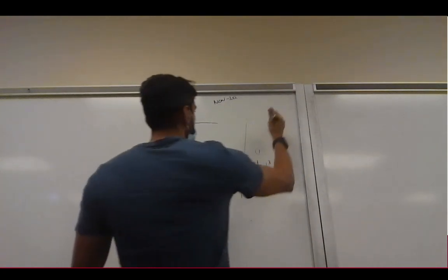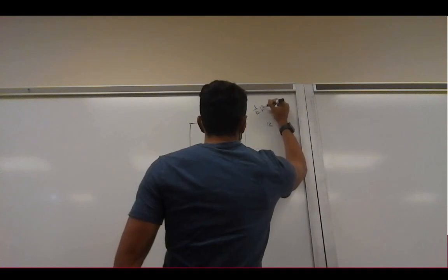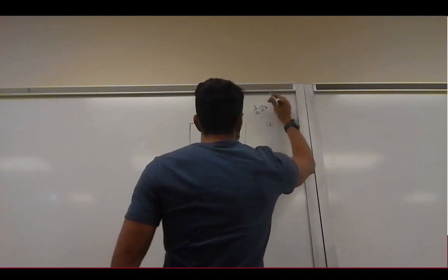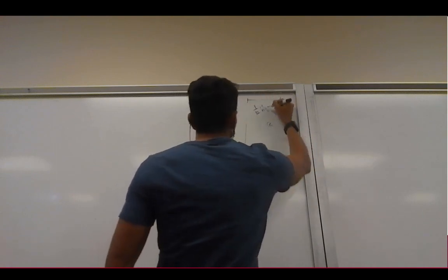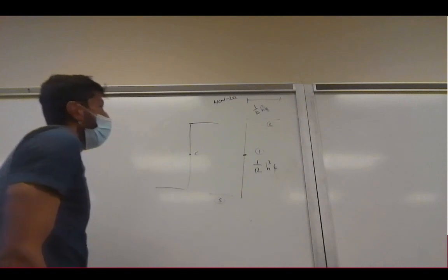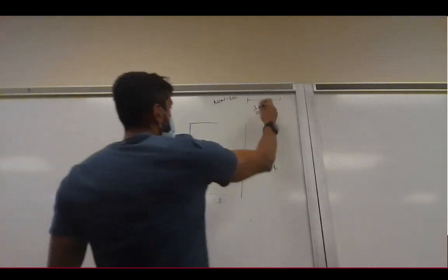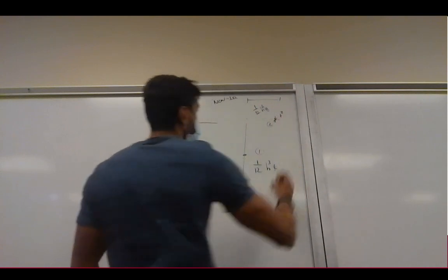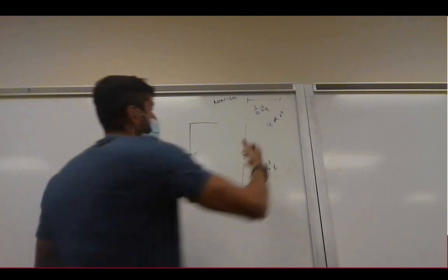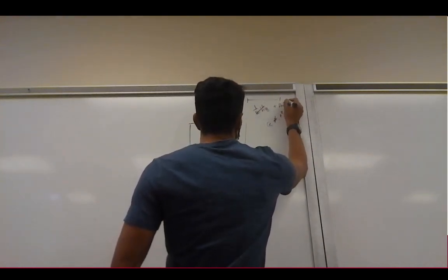So for 2 and 3, here we have again 1 over 12 h cubed b, sorry, a cubed. In this case, the h will be the thickness, and it will be thickness to the third, and we always assume thin walled, so this basically disappears, and we're left only with the AD squared terms.